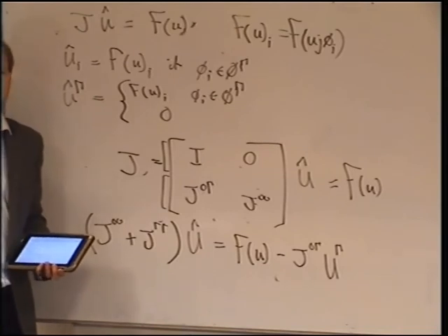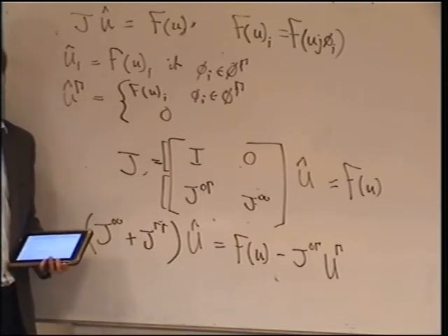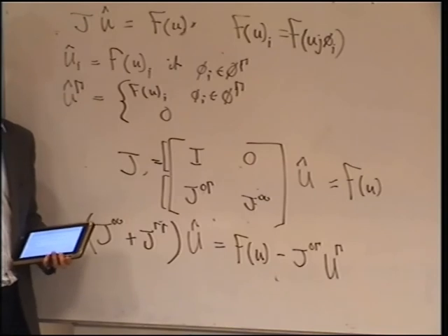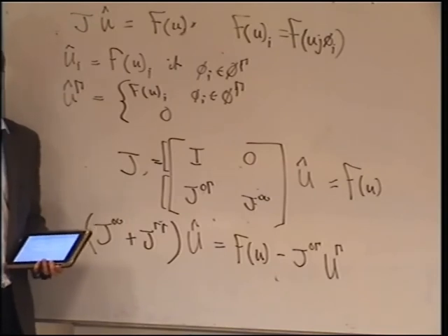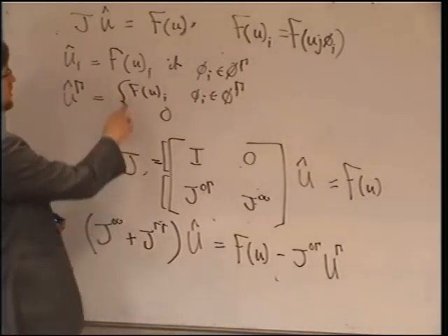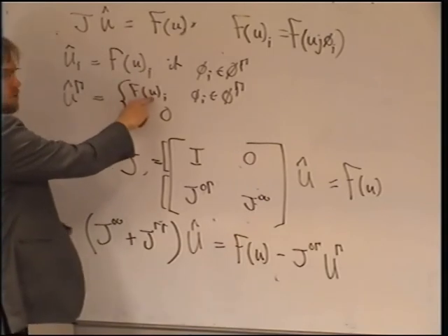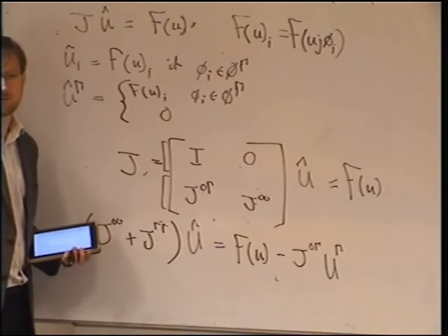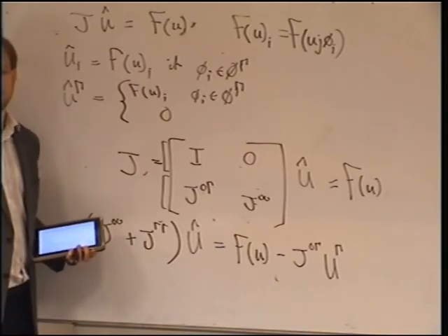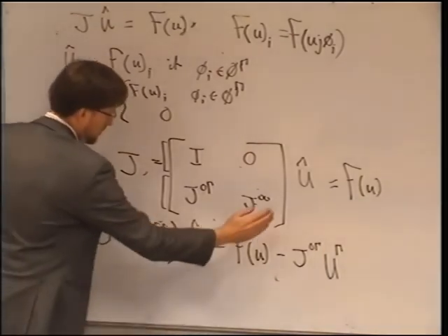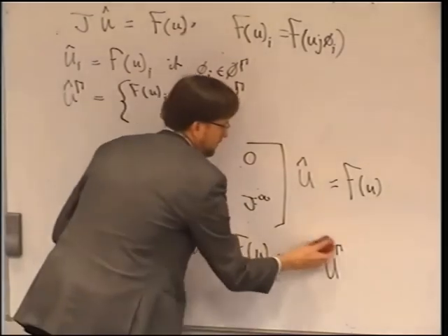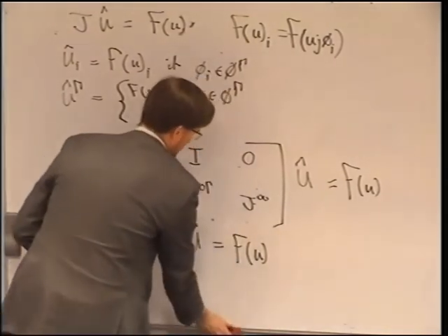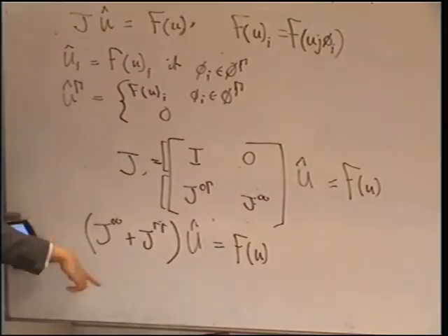So we treat it as the initial guess, but we don't use all of it. Before we start any of the Newton solver process, you change the initial guess values on the boundary condition nodes to the boundary condition values, because you knew how to solve that bit. And then this goes away, and you can just solve this.